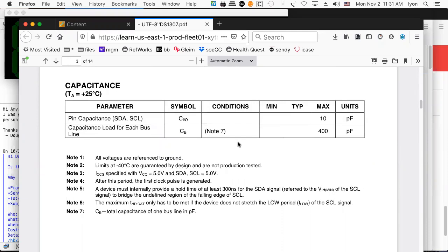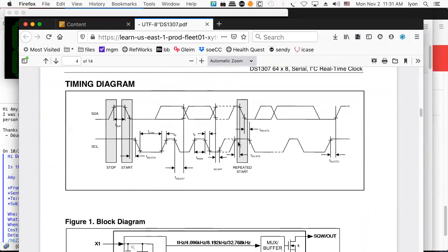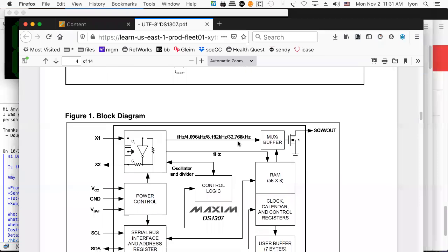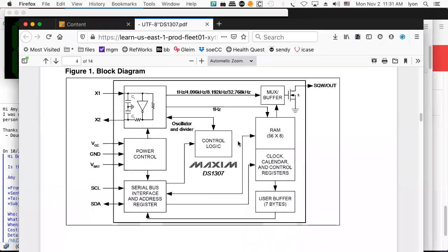There's another thing going on here with this device. It's not using SPI. It's using a 2-wire interface, and that is a little bit unusual for us. So here's SCL, that's a serial clock. Here's SDA, that's serial data, and notice it's bidirectional. So this is our first encounter with the I2C interface. I2C interface is a really nice interface in terms of its simplicity. It doesn't use a chip select. Instead, it uses addresses, which means that devices have to have unique addresses when they sit on the SDA bus.